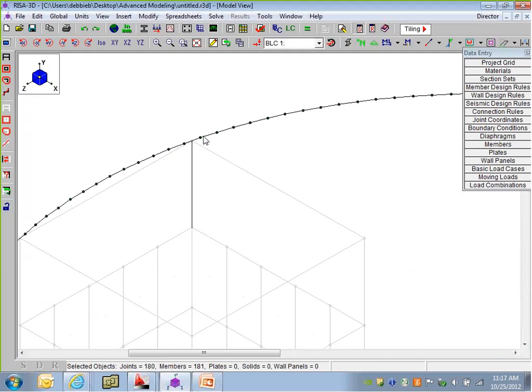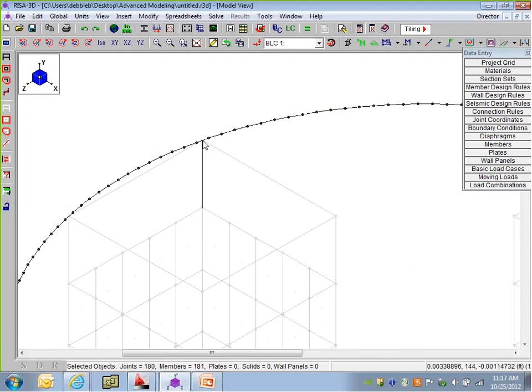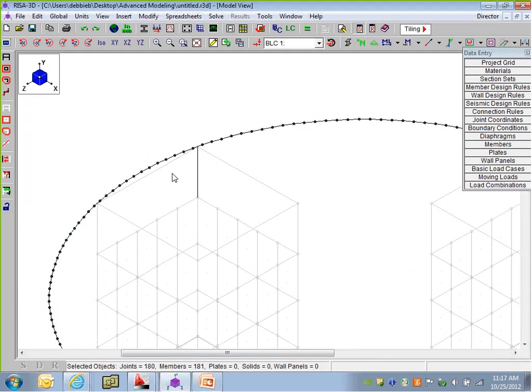It's actually okay, since we have physical members. But maybe later on, if we were thinking plates or anything else, it would just be nicer and smoother if we actually move this over. We can do some measurements, again, using our F5 tool to find what actually the radius is there, so how much increment we need to actually rotate this ring.